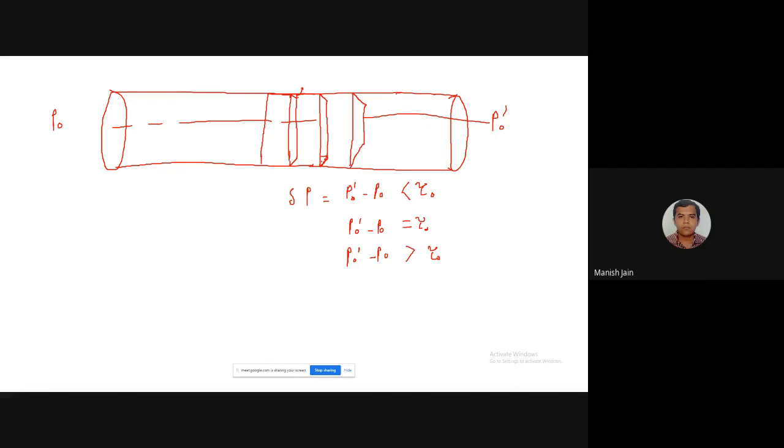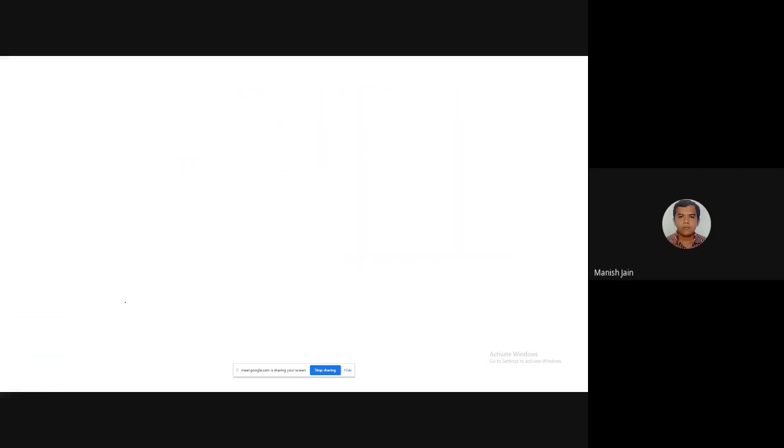After some time, if the shear stress and the pressure drop are much higher, then you have total Newtonian flow. So as the pressure drop increases, you have the transformation from Bingham fluid to Newtonian fluid, based on the value of the shear stress. This is the condition for the movement of the fluid. So we can write here: condition for movement of the fluid.